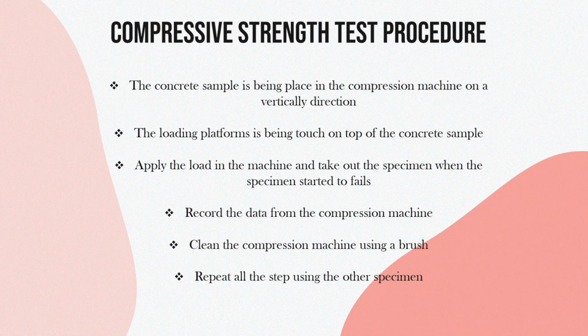Next step is you must clean the compression machine using a brush. Finally, you must repeat all the steps using the other specimen that has been taken out from the curing tank.